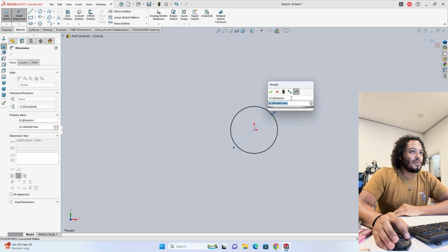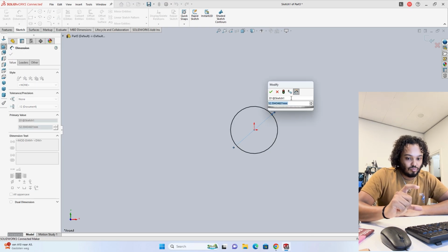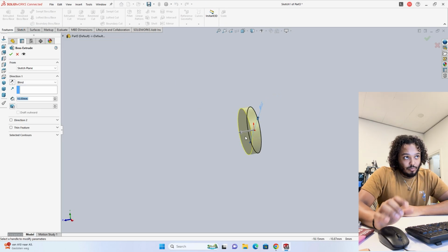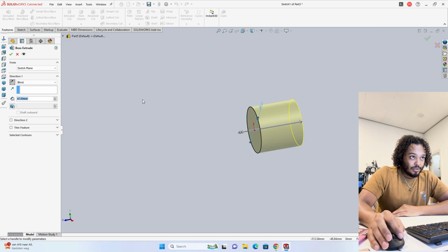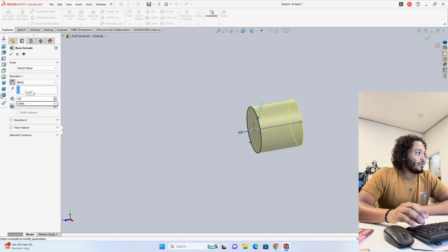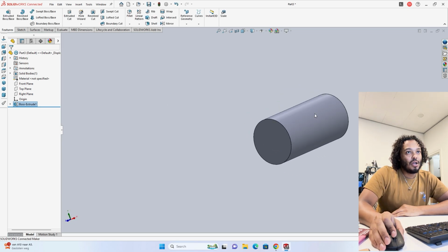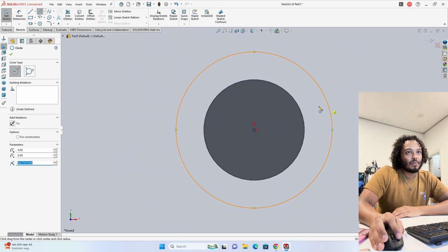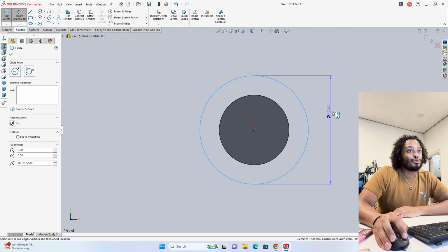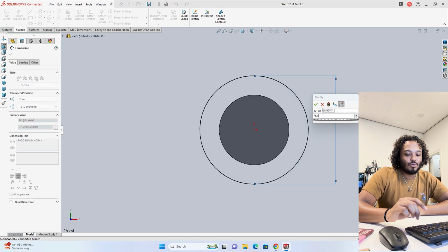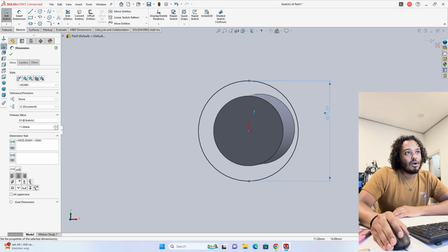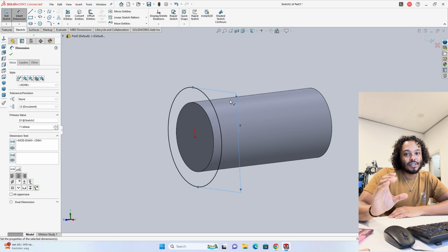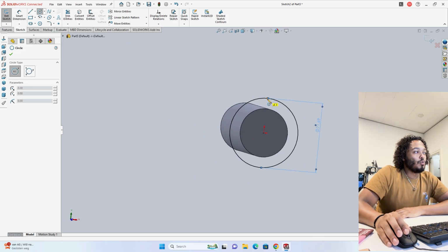So I'm gonna put that at about, I think 50 would be good though. And then we also know that the piston itself is about 86 millimeters wide. So let's say we're gonna start off with 100 millimeter length, I guess. And then the next dimension that we know is the actual stroke, and that is gonna be 71.69. And that is gonna be the axis of rotation of where the actual connecting rods will be attached to. That will basically dictate what those dimensions are.